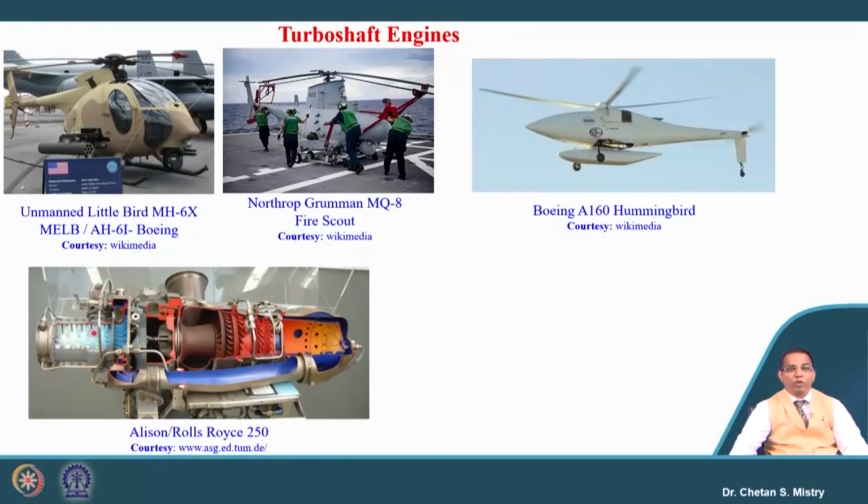This turbine is rotating the compressors, both the axial flow compressor as well as the centrifugal compressor, and this is the power generating unit. We can say it's a power turbine, and from here you are having the exhaust. So, there are special kinds of construction also. It is not always necessary that you will have the construction followed by compressor, combustion chamber, turbine and then nozzle. Here it is an exceptional case.